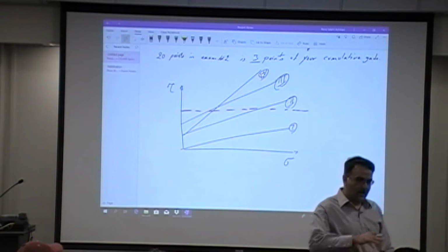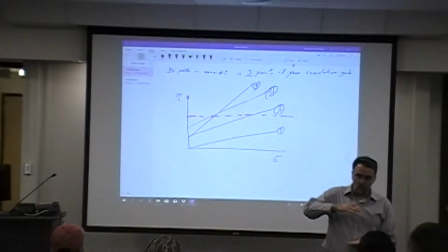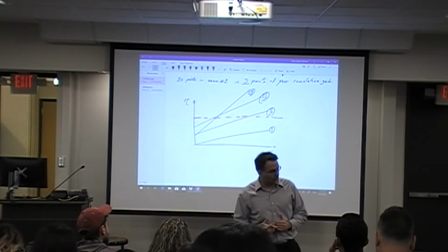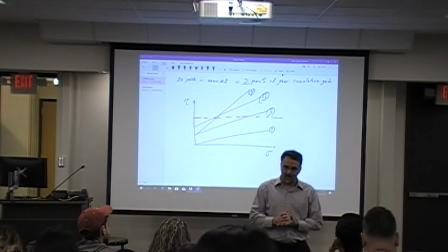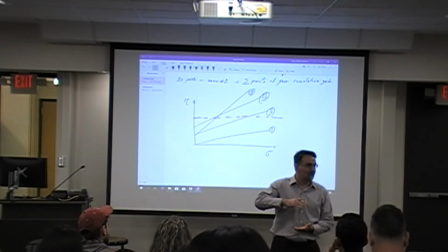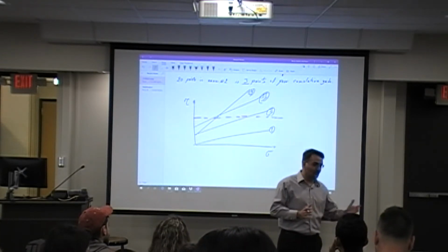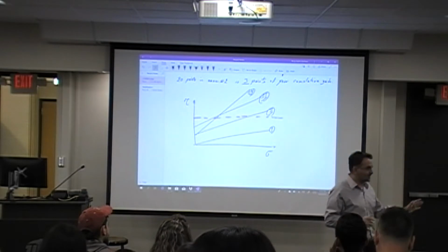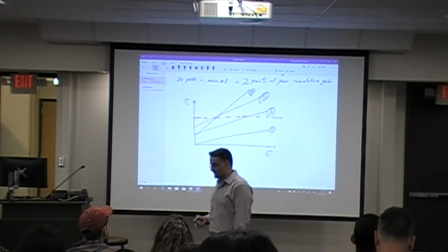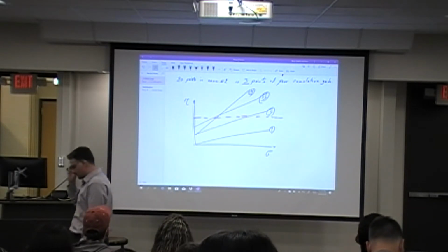Remember we talked about if you apply multiple loads on a bucket of soil, what happens? Reduction of the void content, right? Better interaction. Therefore, the higher the magnitude of the stresses, the higher the strength of the material, up to a certain point before you see the failure take place, right? So that's basically what it means in terms of the stress sensitivity of the material.